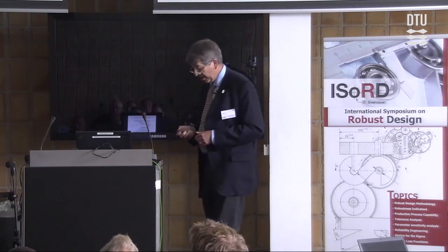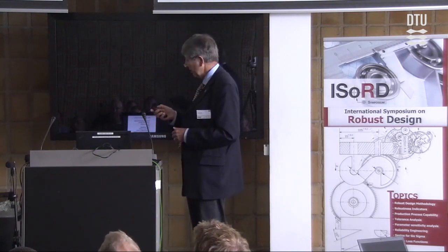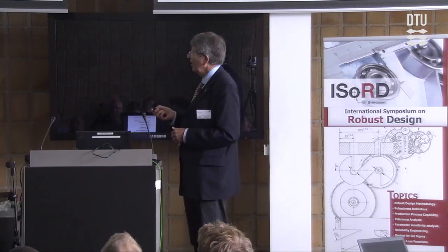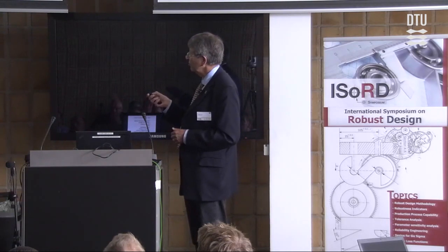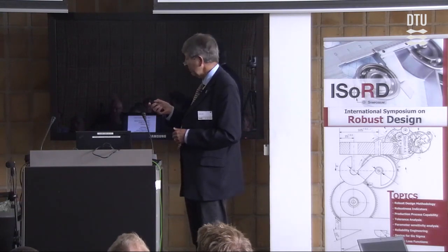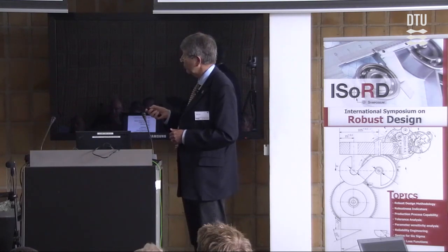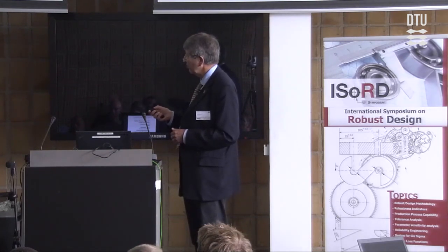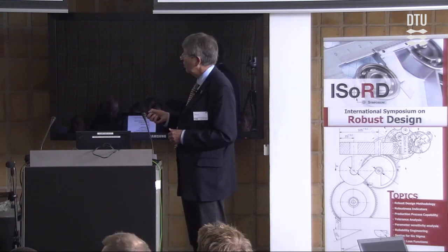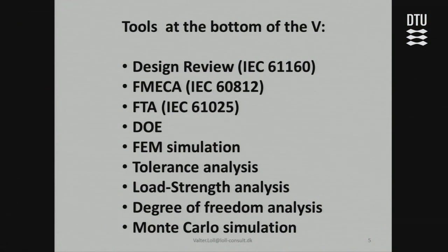And which tools could that be? Design review, there's an international standard on that. FMEA, which will be discussed also here, there's also an international standard on that. Fault tree analysis, also an international standard. Design experiments that I will come back to. Finite elements that we just saw. Tolerance analysis that has just been discussed. Load strength analysis that I'll come back to. Degree of freedom analysis, which has also been mentioned today. And Monte Carlo simulation. So that's just some of the tools that you can use in the detailed design.